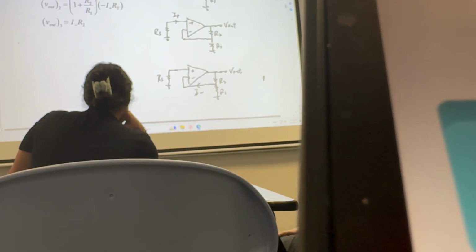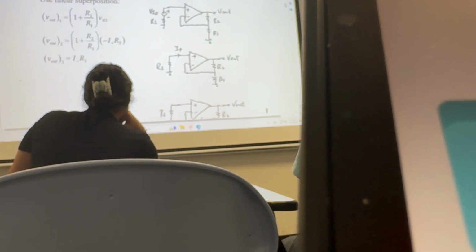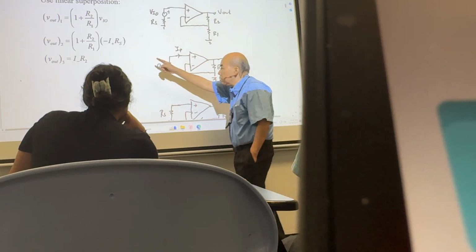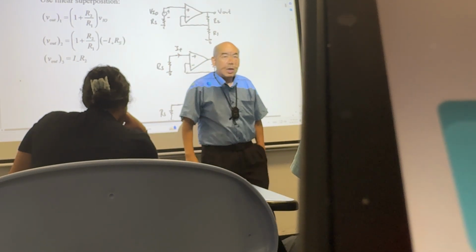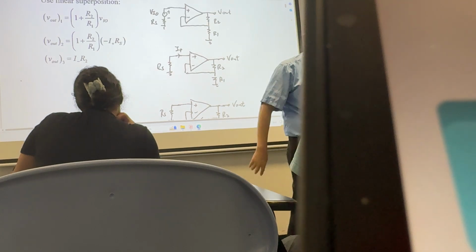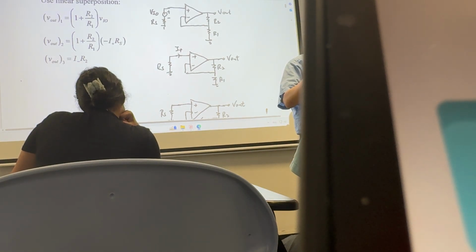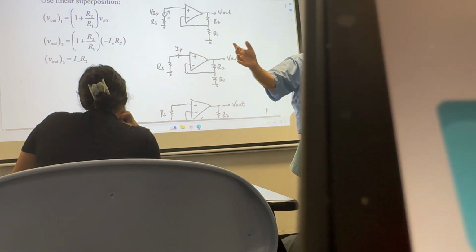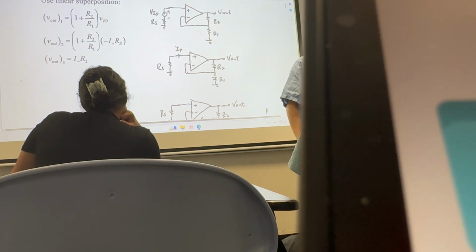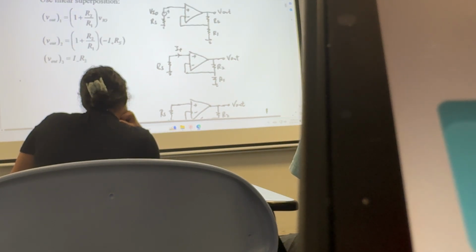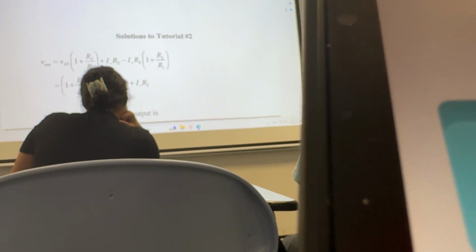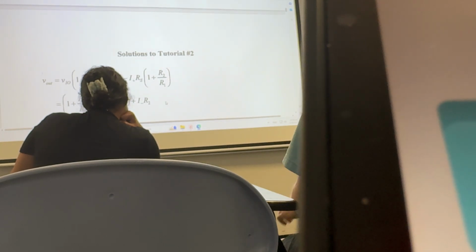Now what is the interpretation? If you compare the two bias currents, this is a negative, this is a positive, right? Under the superposition theorem, you sum everybody. But you can find that one of the offsets counteracts another offset due to the different polarity, right? So what happens if you deal with different polarity? You reduce it, right? If you properly select the magnitude. So after doing that, you sum everybody together, right? So this is your answer.